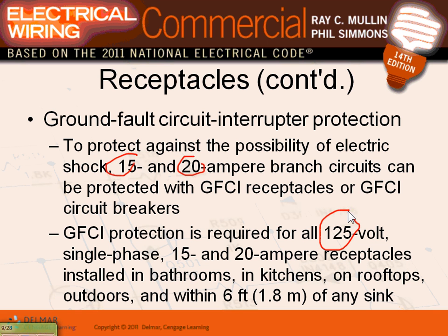Yeah, and does our spec tell us what size of receptacle? They don't say 20 or 15. No, they don't say that one. So all the receptacles that we're installing in this project are 20 amp receptacles, typically standard. Though they do talk about GFCI, for example, one receptacle for every 2 sinks in the bathrooms. They say GFCI in it. Exterior, mechanical room, GFCI. So they listed a few GFCI locations here, which is directly from the code: wet locations and bathrooms.